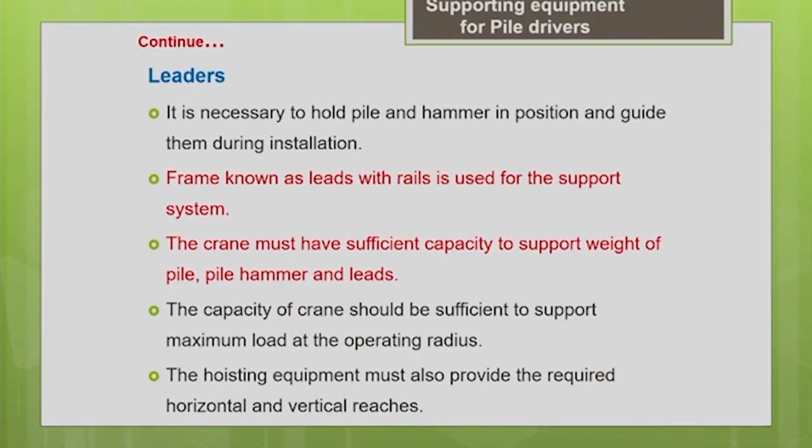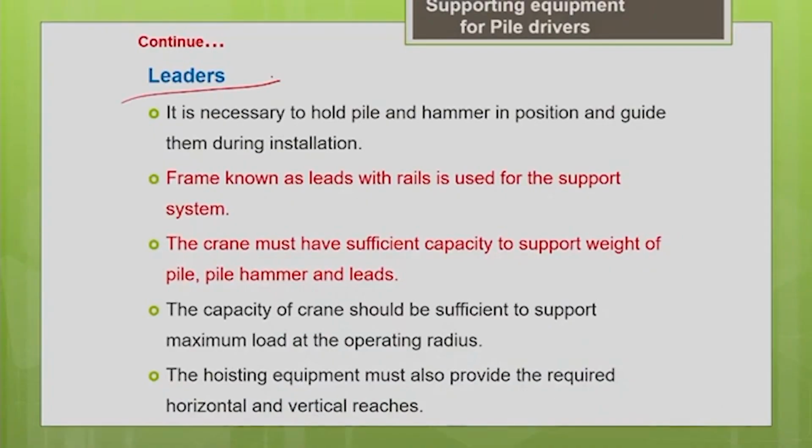So, as I told you, it needs some supporting frame structure to hold everything in position so that you can maintain the proper alignment of the pile. For that you need the help of the leaders. It is necessary to hold the pile and the hammer in position and guide them during installation. For that we need the frame known as lead.